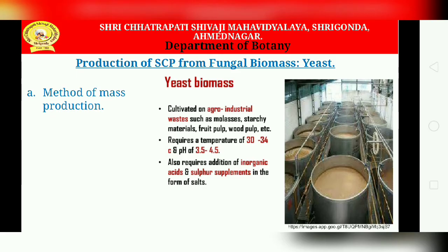The molasses is placed in the fermenter, diluted with water and then pasteurized. Compounds added to this solution are ammonium sulfate, diammonium hydrogen phosphate, magnesium sulfate, biotin, thiamine, or yeast extract in traces. The fermenter is then inoculated with a small amount of the desired strain of yeast. Sterile air is driven into the fermenter by motor driven propeller pumps.